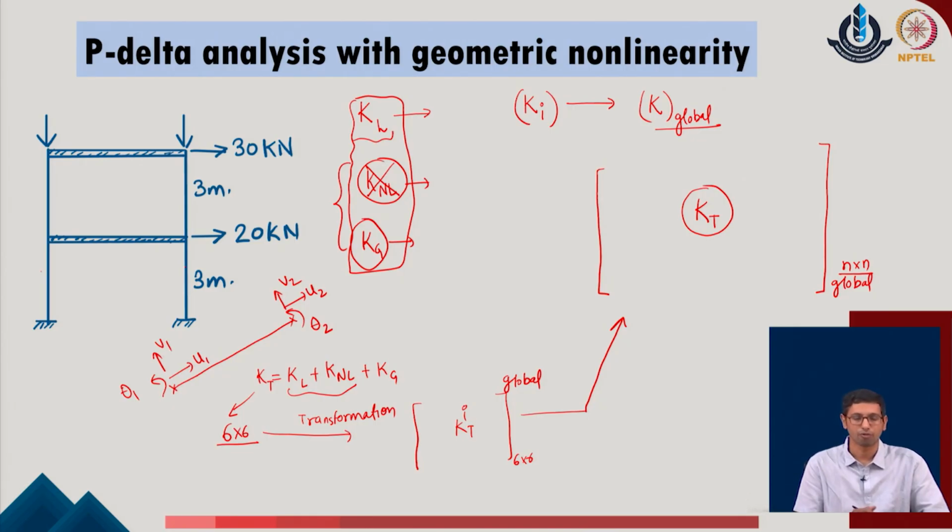the given system. One more simplification which the user can make is that mostly it is the columns which are subjected to the compressive loads. So, when we go with the calculation of the geometrical stiffness matrix, I can concentrate only on the contributions of the geometrical stiffness matrix coming from the columns of the given system. I can leave my beams without the contribution of the geometrical stiffness, because in most situations they are not subjected to any kind of in-plane compressive loads. So, with this idea the overall procedure of the analysis can be simplified, and that becomes much faster also in the software systems as well as in the computer codes.